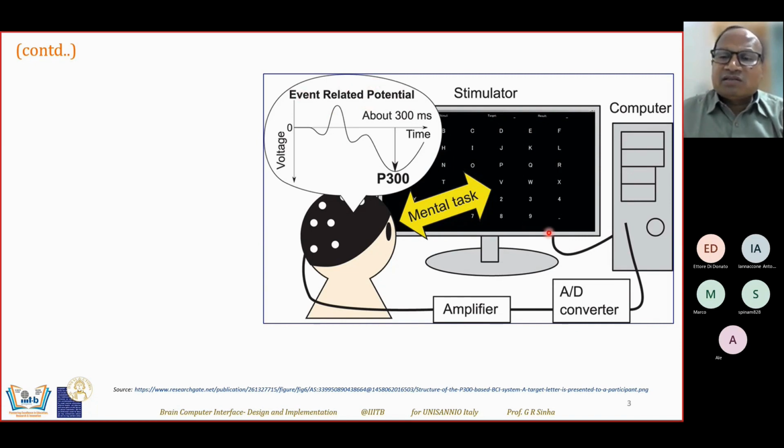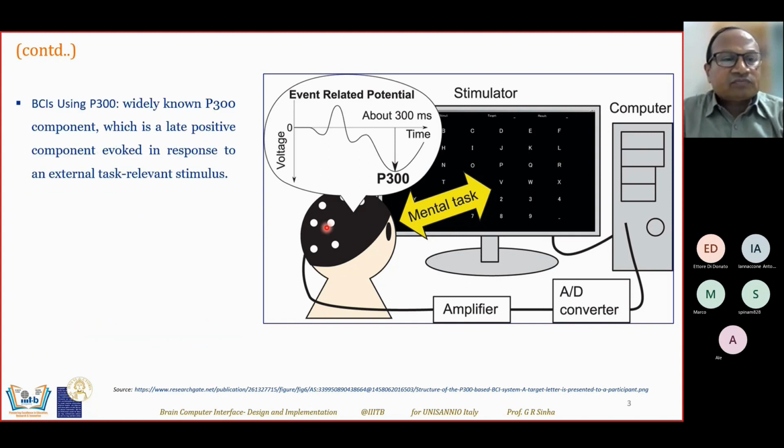And then the other thing is similar, that the data goes to the AD converter, then amplifier. You know it very well. Rather, it goes to the amplifier, then it goes to the analog to digital converter, because the signal strength is weak. So today we are going to talk about this particular area, and the electrode area, which are actually the design and implementation part of BCI.